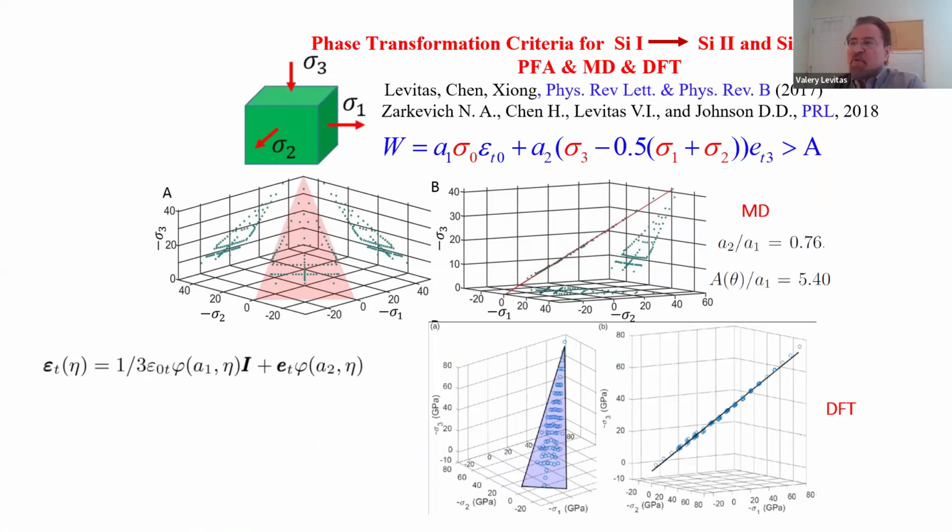That is why we developed four-scale theory. At atomistic scale, our goal is to derive lattice instability or phase transformation criteria on the action of all 6 components of stress tensor. It seems to be impossible due to large number of combinations, but actually we developed continuum phase field approach, and within this phase field approach we predicted analytically this criterion, so now we need just to check it.